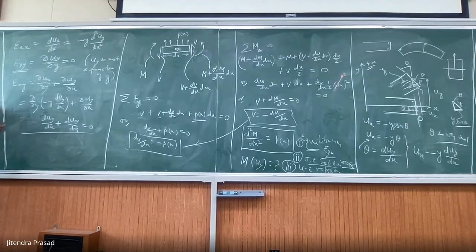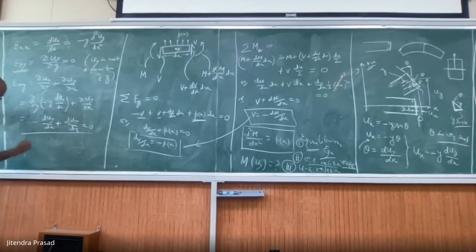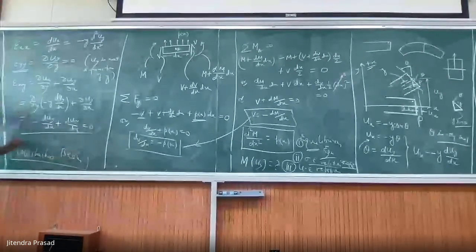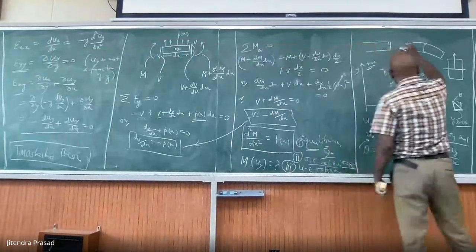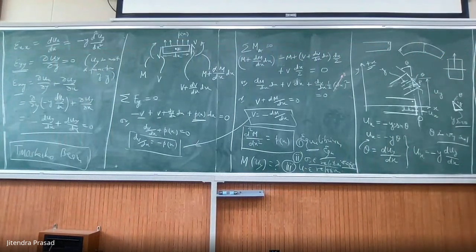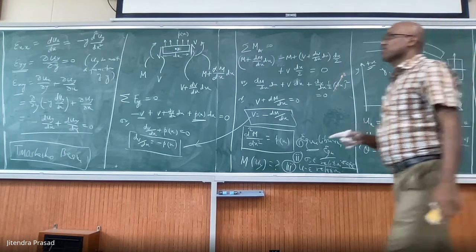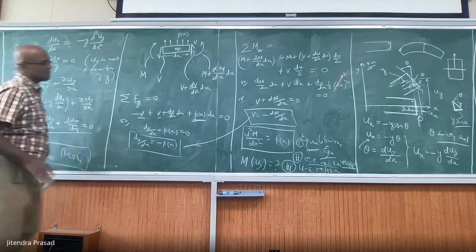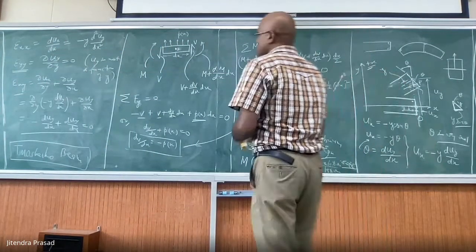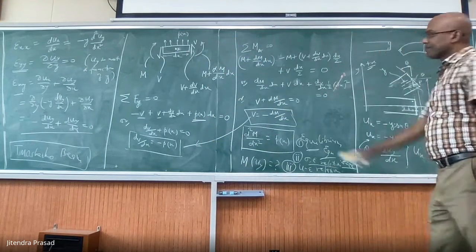These are the problems, and hence Euler Bernoulli has problems. Hence these are corrected, and there is something called the Timoshenko beam, which gives all corrections, and for that this term is not zero. Then this assumption is not true that it is at 90 degrees, because you know that if there is a shear, then the corner is not 90 degrees. So Timoshenko beam theory actually modifies the original Euler beam theory, and they propose that the shear strain is there, and hence it is more accurate.